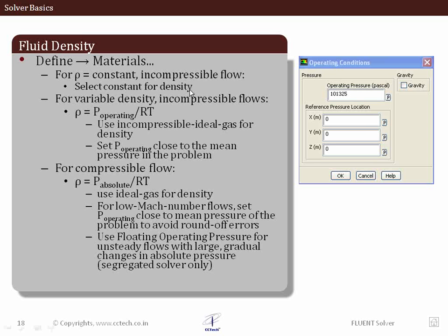Let's specifically look at the fluid material density. The fluid's density can be either a constant, or it can also be chosen to be an incompressible variable density. When I say incompressible or compressible, usually the fluid's compressibility does not necessarily mean that the flow will also be compressible. The compressibility of a flow is defined by whether the density of the fluid varies with the flow pressure. Unlike a compressible fluid whose density is simply varying, and then you classify it to be a compressible fluid.